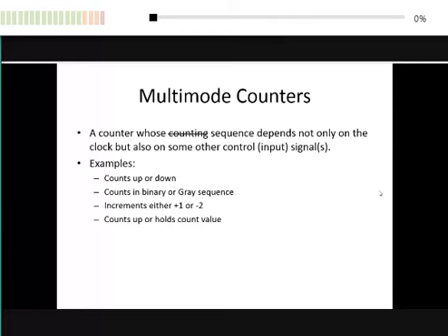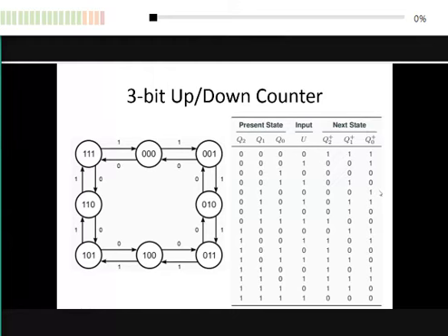All right, example: count up, count down. Not interesting. Let's see, this is a 3-bit up-down counter. Horrible. Why horrible? Because you need an input to decide the direction. So now it means your K-map is a 4-input K-map. 4-input K-map is quite big, isn't it? But in exam, they may even ask you 5-input. But I don't recommend it. Never mind, let's see this.